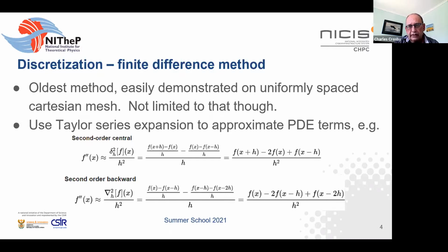They easily become unstable, they destabilize the equations. So in practice, what often happens is you start off a solution using first order schemes, get the solution to a reasonable level of accuracy, and then switch to a second order scheme to refine the solution. So it's really useful to have a CFD program that allows you to make that switch while the program's running, so that you don't even have to stop it.